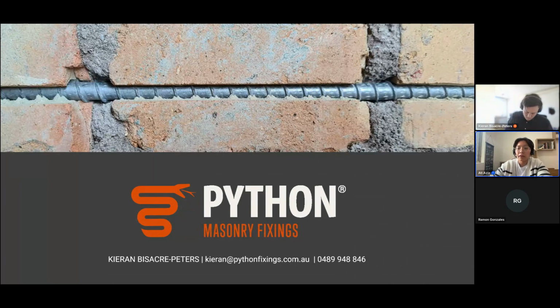All right. And then a question from Ersin. When crack stitching, how do you cater for the central skin of a 3-skin brick wall? So you can grind out the mortar joint as far or as little as you need to lay your crack stitching wires in. For a multi-wire thick wall, I'd suggest grinding out maybe at least 1 brick depth. And you can lay as few or as many wires into the joint as you wish to strengthen it up. Maybe half the depth of the wall would be sensible. Lay 2 or 3 stainless steel wires in, epoxy them up, and that would give you a robustly stitched crack.